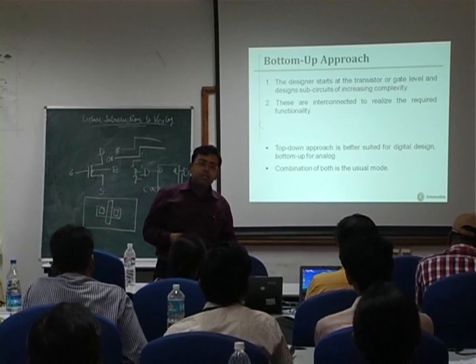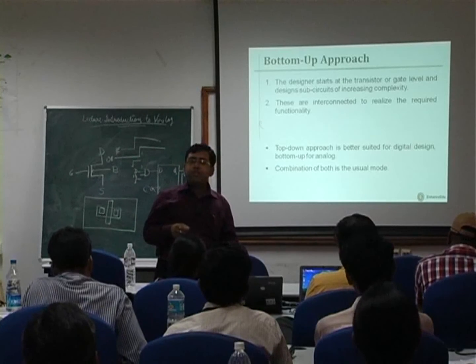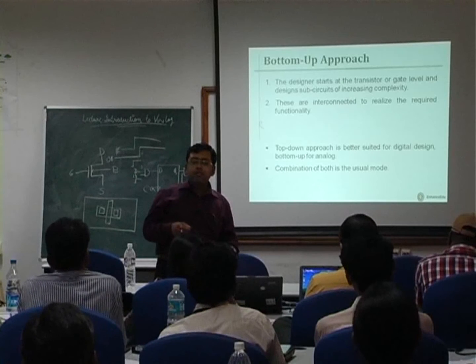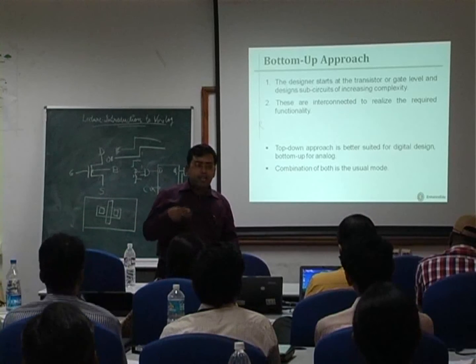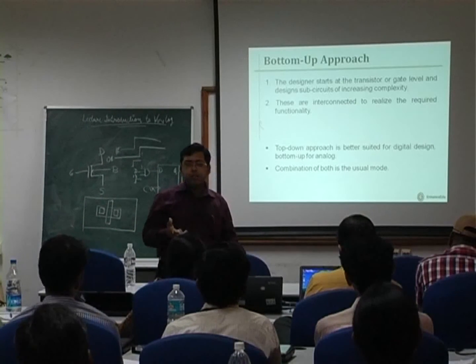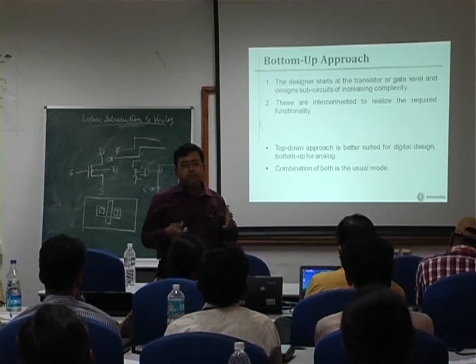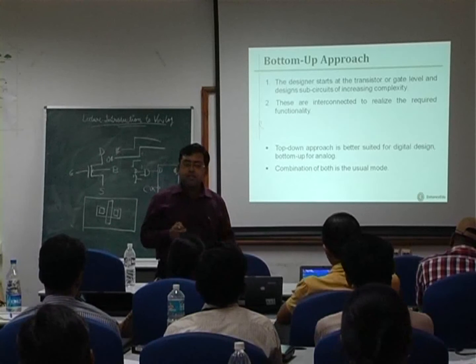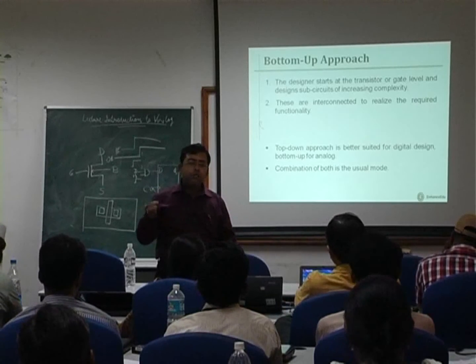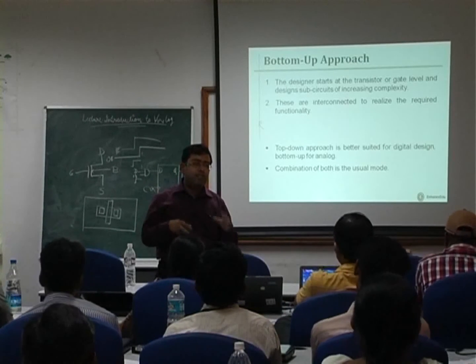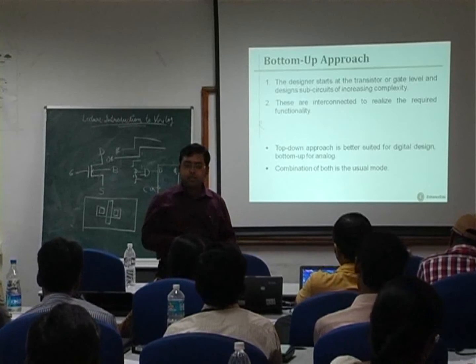On the other hand, in case of bottom up design, you accurately design the circuit, because you start with a single MOS transistor, check whether the behavior of the transistor is correct or not, and you go on incrementally adding components to it, ultimately arriving at the whole circuit.